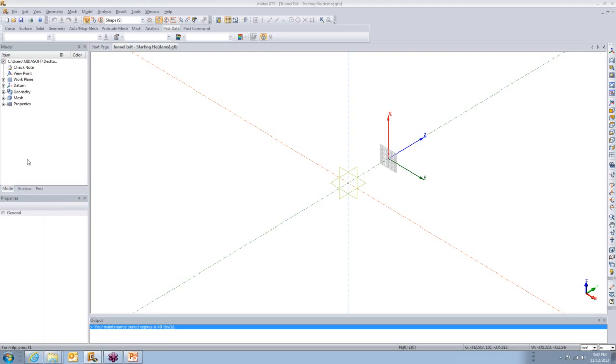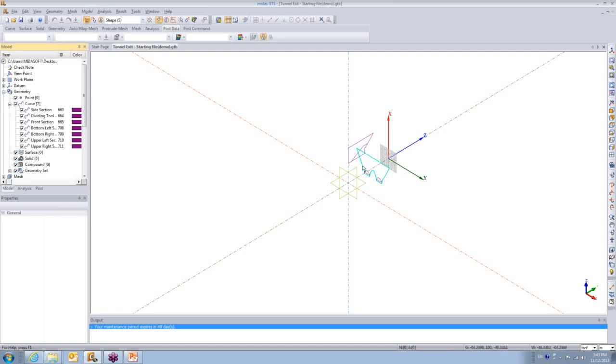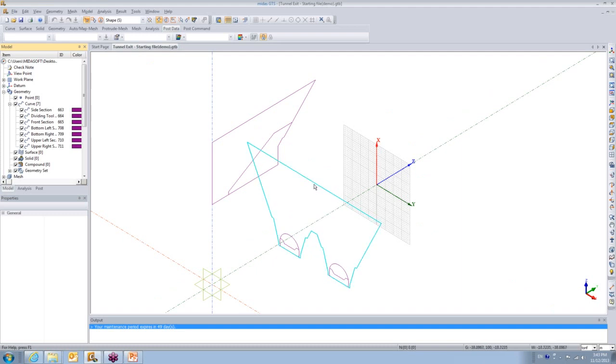So this is how the software looks. In the modeling part, I have defined some material properties and attributes for the ground conditions, as you can see here, and I have brought in the basic geometry from a CAD source. So let me quickly show it to you. These are the basic outlines that I would be working with, which can be easily extracted from or brought in through CAD sources. If you don't have CAD sources like DXF files, you can create these lines and everything easily from the graphic user interface also.